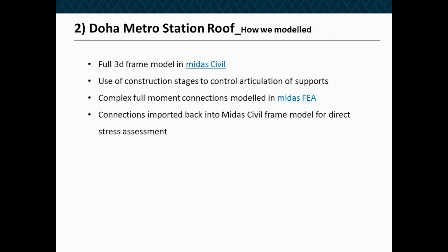Okay, so it's a standard 3D frame in MIDAS with normal beam elements, generally speaking, a few links that I've mentioned, and then the complex connections we wanted to do in solids, so we used another part of the MIDAS family called FEA. I don't know whether any of you have come across FEA. It has a slightly different user interface to MIDAS Civil.